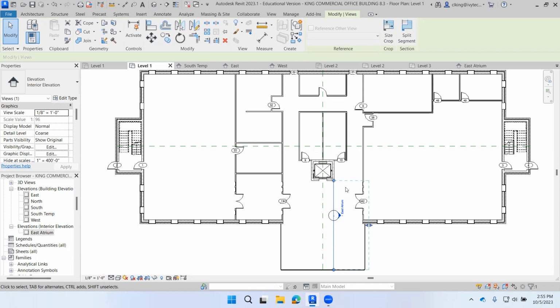Adjust the control lines for the elevation tag as shown in figure 8-3.4. Drag the cutting plane extent of view line to the location shown. Make sure that the far clip plane extends past the door alcove, otherwise it will not show up.